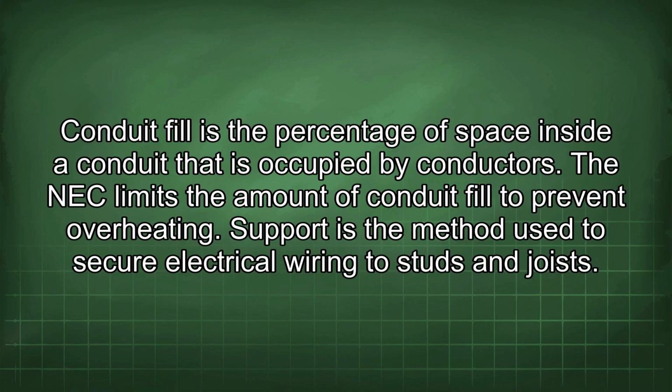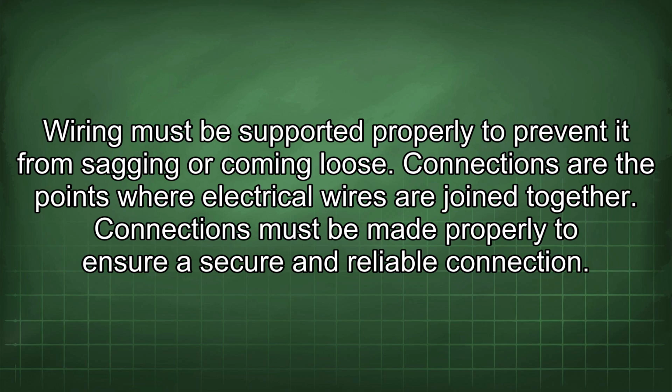Conduit fill is the percentage of space inside a conduit that is occupied by conductors. The NEC limits the amount of conduit fill to prevent overheating. Support is the method used to secure electrical wiring to studs and joists. Wiring must be supported properly to prevent it from sagging or coming loose. Connections are the points where electrical wires are joined together.